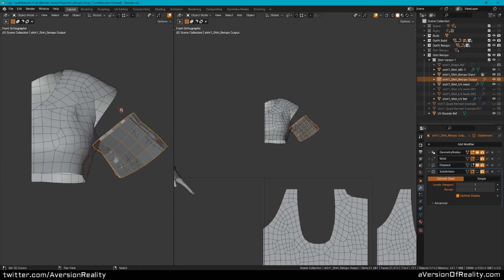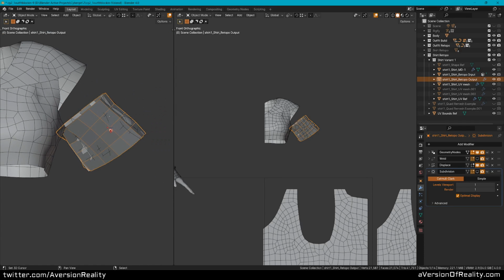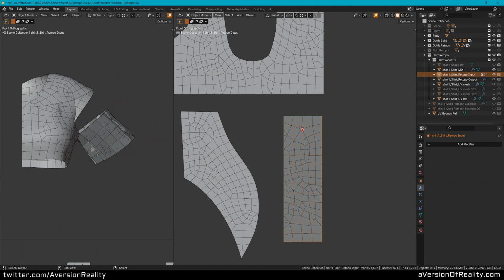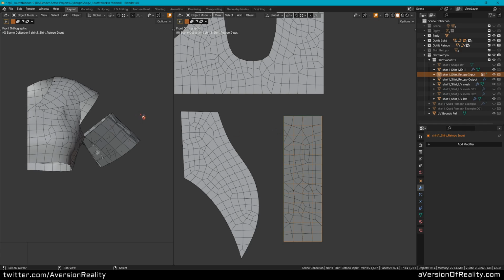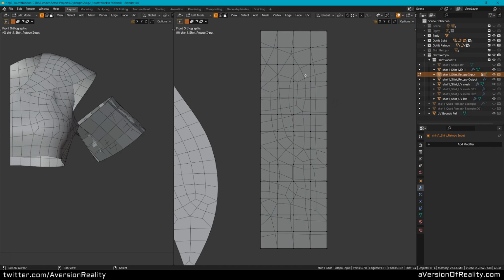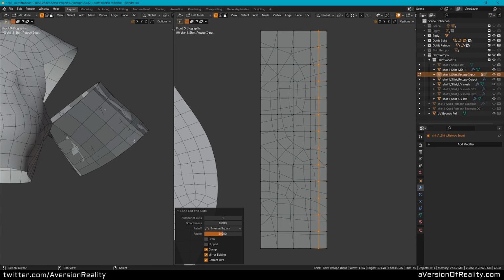And, well, why does 4 do? Why this many loop cuts in each direction? It's squares, that's nice, but how do I know that I need this many and not more? Even on something as simple as this, before I know what I need, I have to start asking myself questions like, what is this for? For example, do I want this to be even squares? Do I need another loop at the edge here because I'm going to add some trim, or make it look like the shirt's rolled up again, or bevel this or whatever?